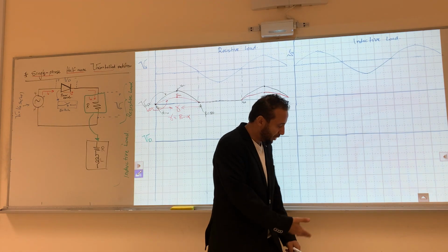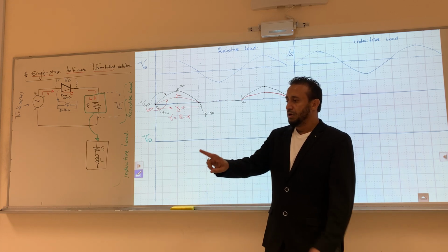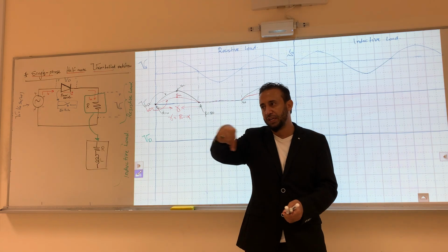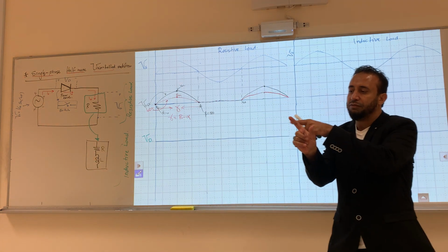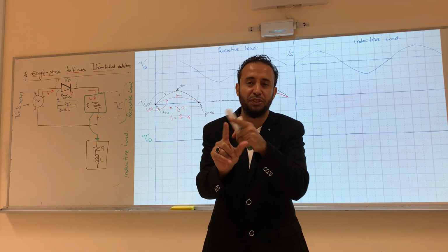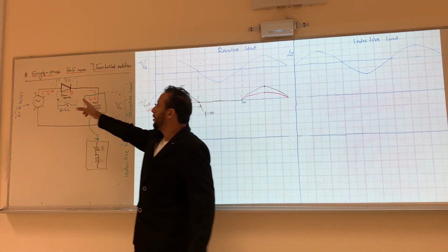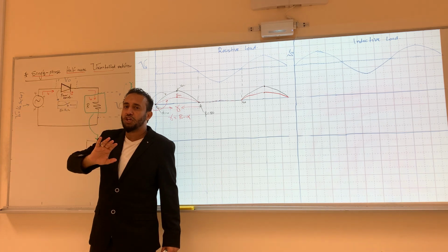If you look at any plug, you measure the voltage, there's a voltage. But if you connect a wire, if you close the circuit, and try to get the voltage at the same point, no potential difference, no voltage. So when this is a short circuit, when it's conducting, if you try to measure the voltage, it's 0.